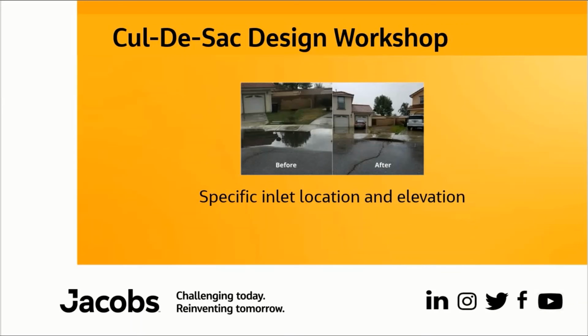And this is an example of where this workshop would come in handy. As you can see here, we have a cul-de-sac that seems to be having some drainage issues, but it's also tied up by the fact that we already have some driveways, we have an inlet that's already existing there, and if we wanted to rebuild this cul-de-sac, we would have to make sure that everything was being directed to this inlet and that none of the water was going to maybe some of these driveways.